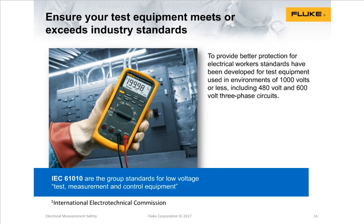And we'll talk a little bit about what happens and what causes that arcing incident and the type of tool to use. So these are environments that are rated in 1,000 volts or less, 480 volt and 600 volt three-phase circuits.